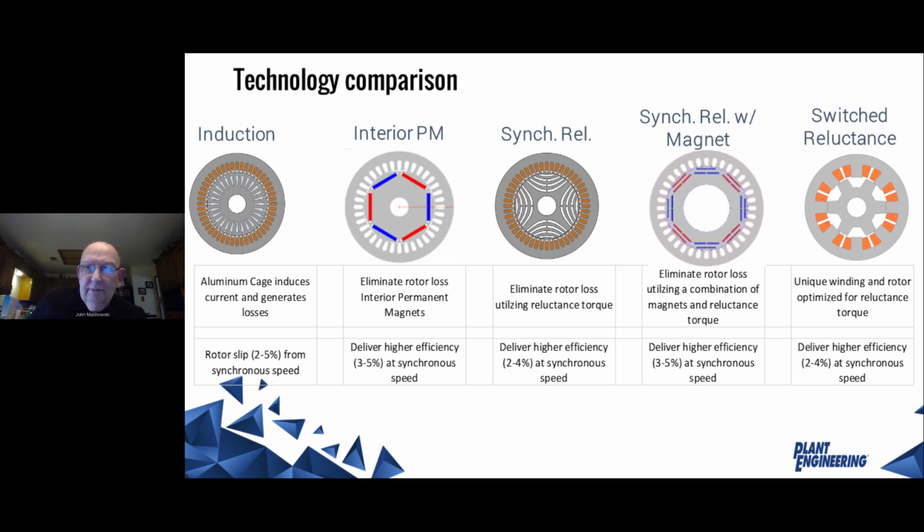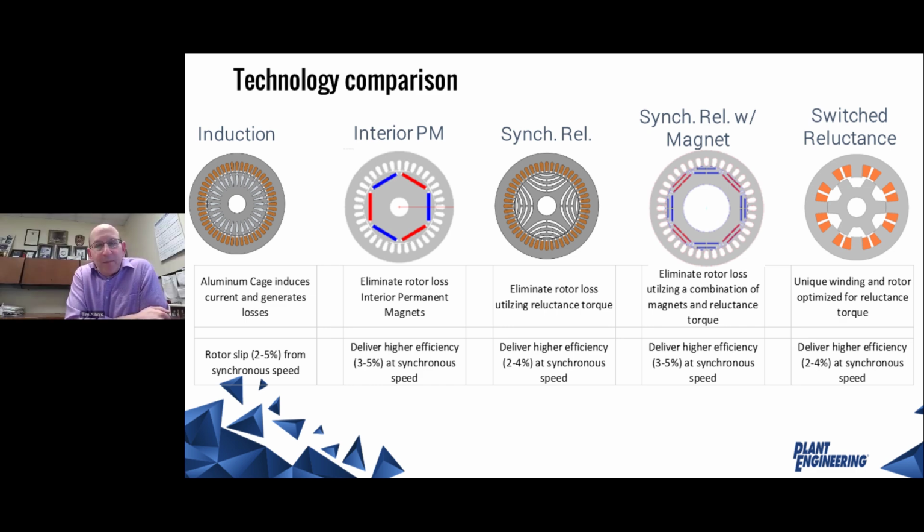Sure, John. Absolutely. Yeah, I skipped over that on the previous slide. The one thing I just want to make sure everybody understands is we're not talking about, I was going to say, your grandfather's synchronous motor. I have to be careful because I am a grandfather, but what I mean by that is I'm not talking about your 5,000 and 10,000 horsepower synchronous motors that actually have a wound field on the rotor that allow for power factor correction. I'm talking about mostly 500 horsepower and smaller, with a whole bunch of it being 20 horsepower and smaller synchronous motors that usually in many cases use magnets, or they're using reluctance torque.